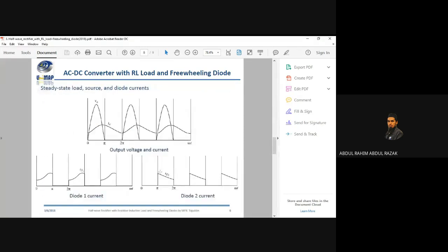That's why you can see the linear decrement here, down to the full cycle. Then when the next cycle starts, it rises up gradually again, following a sine wave pattern and then reducing in a linear curve. The sum of your output will be like this: sine, linear, sine, linear. This is the current you can see from diode 1 and diode 2 separately, and this is the current you can see from the output of RL.